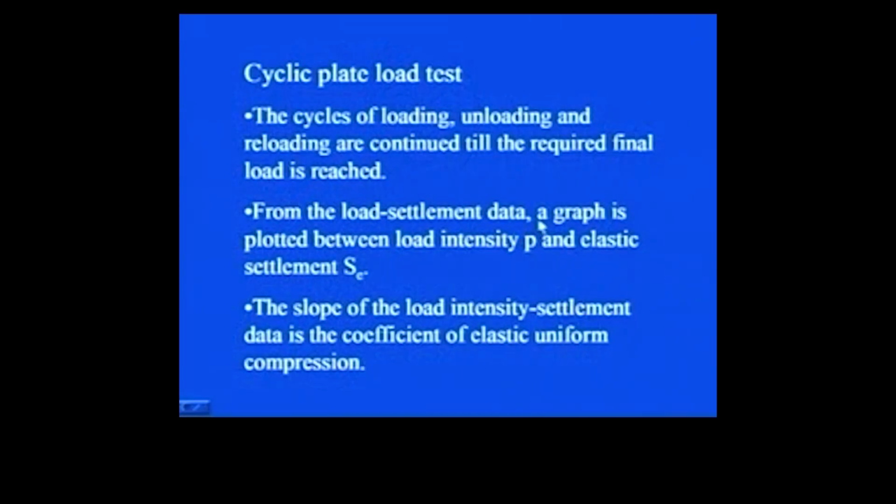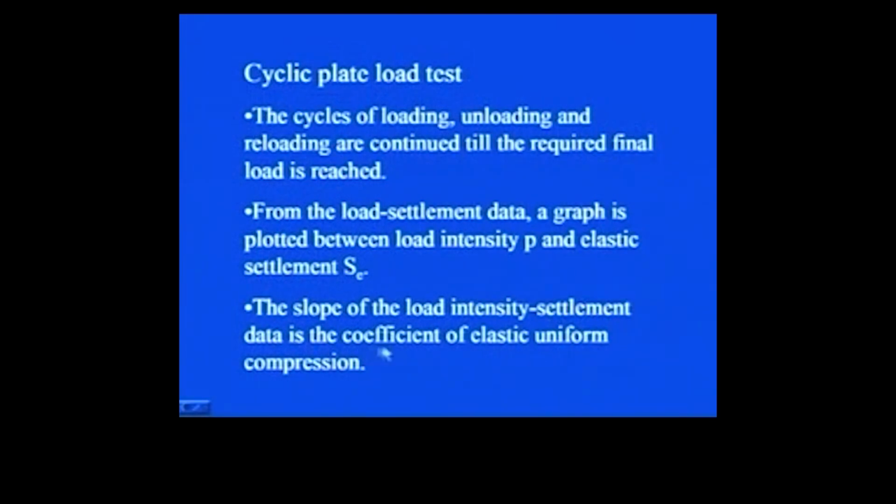From the load settlement data, a graph is plotted between load intensity P and elastic settlement SE. Whenever we allowed the plate to rebound, we noted down the final settlement to see to what extent it has rebounded. From there we can get the elastic settlement, because whatever it has recovered is the part of the settlement which is elastic; the remainder is plastic settlement. So the elastic settlement we can get corresponding to each loading intensity. The slope of the load intensity settlement data is the coefficient of elastic uniform compression.